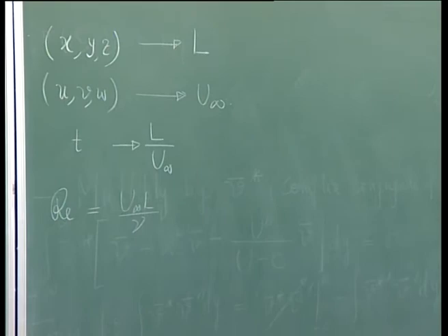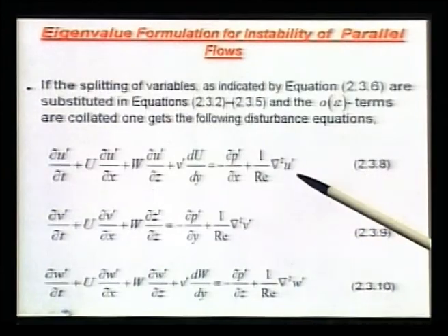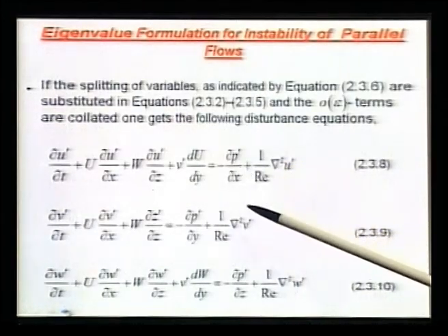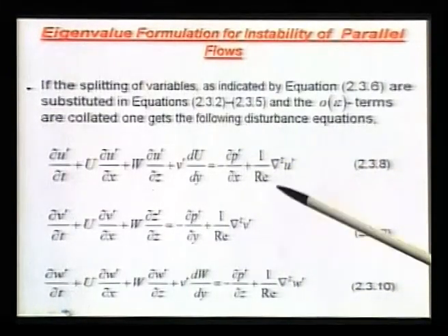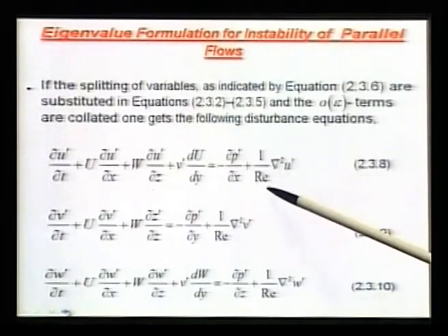And that is why you see that P will be non-dimensionalized with respect to what? Rho times u infinity square. We are focusing our attention on incompressible flow. So, rho is a constant, so I will non-dimensionalize the pressure by rho u infinity square. That is what we are getting here, that del p del x, rho has disappeared, and you get in front of the diffusion term 1 over Re.